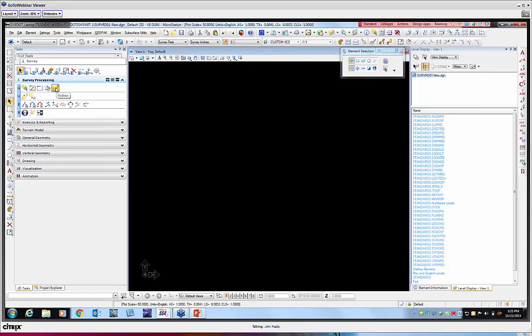It also gets done automatically as you make edits, but anytime you bring in data or change annotation scale, you may have to end up doing a survey redraw. Also note that if you do a survey redraw, it revisits the feature definitions and will reset any kind of rotated cell back to its original position. So things like signs and other points and cells that you want rotated to different positions, you want to do that at the very end because survey redraw will reset those.